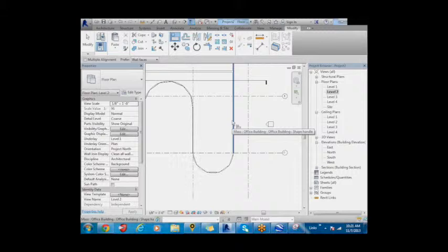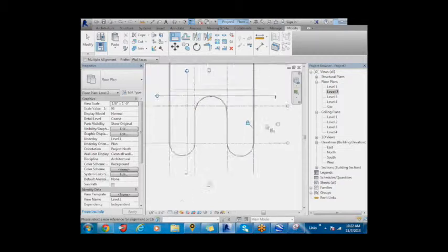Typically, and that's kind of what I'm used to, you put the grid lines before you put the buildings, because you have an idea of an outline of what you want to build. So you know, there's going to be a space between grid line 1 and 2 of, I don't know, 60 feet, and then 70 feet. So you put in the grid ideally, and then you put in the dimension between them. When you're drawing your walls, you trace your walls to those grid lines, and then you put your columns there and stuff. But because of the way we structured this, we're putting it afterward, which you can still do, it's fine.